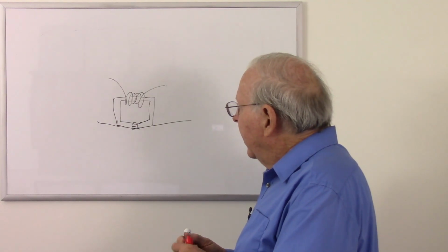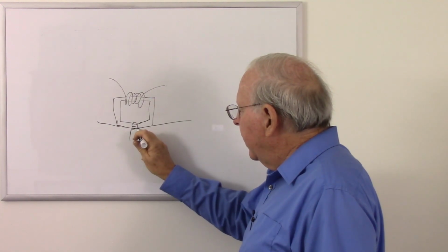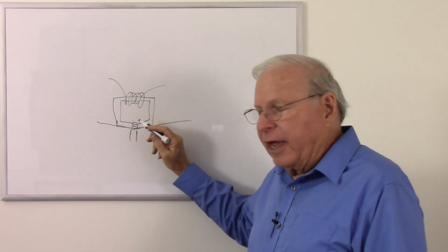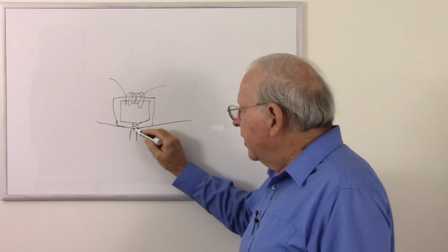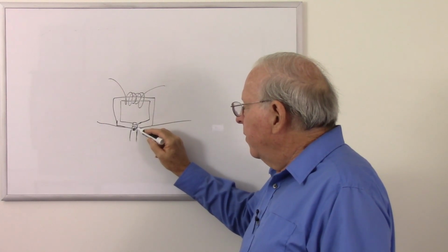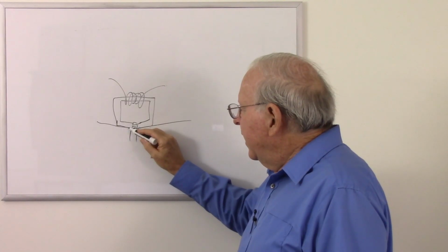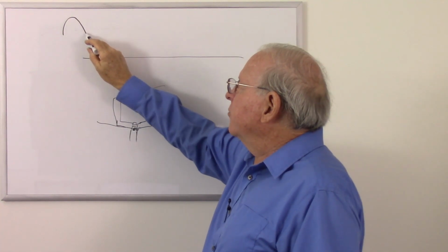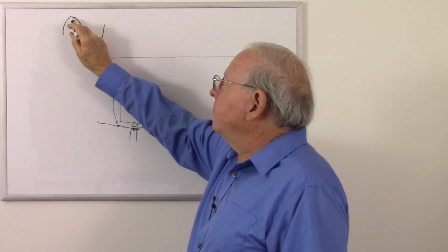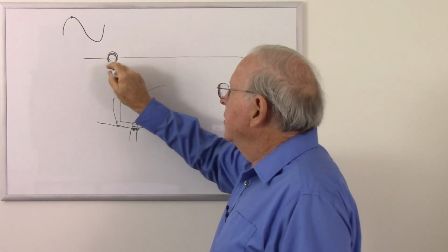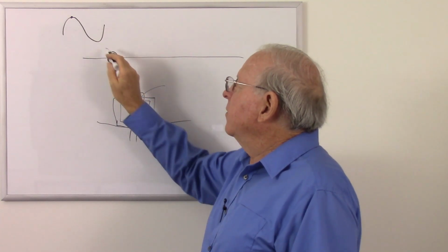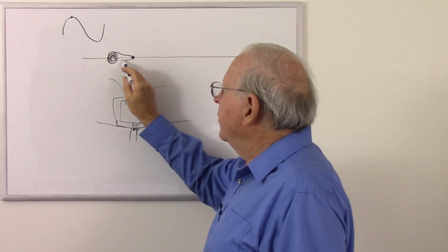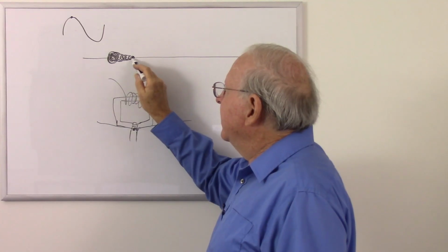So as we magnetize it, look at the width of this gap I put here. Well, as that tape is moving by, we have an alternating current going in there, and as we're magnetizing it, well, we're magnetizing it strong right here, and then that moves away, but then we're magnetizing weaker, and if it doesn't move away fast enough, let's just draw the tape here. So we're trying to record a sine wave, let's say, and let's say we're just right there, so we have a very strong domain there, and then we're trying to get weaker and weaker and weaker, let's say down to here, and in between there, well, we have a lot of overlap as that goes.